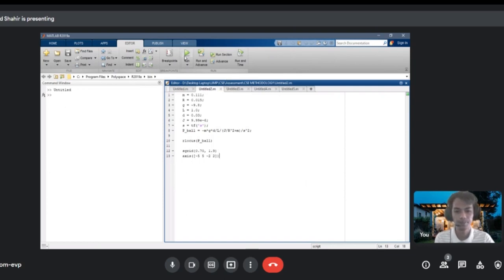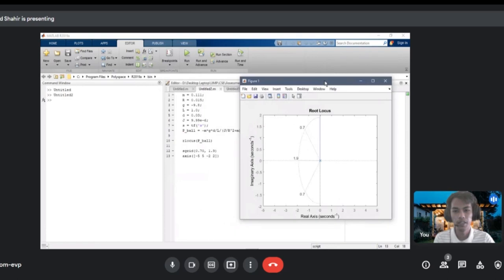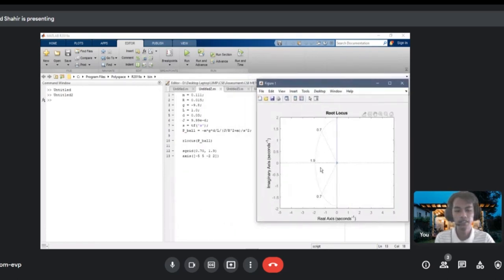So this is my root locus. The area between the two diagonal lines represents locations where the percent overshoot is less than 5%. The area outside the curved line represents locations where the settling time is less than 3 seconds. Note that no region of the plot falls within the design criteria. To remedy this and bring the root locus into the left-hand plane for stability, we will try adding a lead compensator to the system.